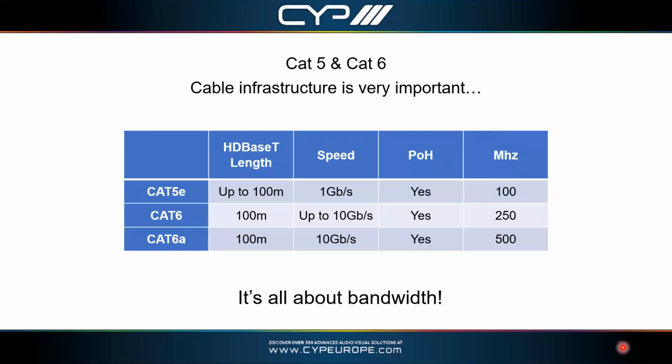Yeah, over the years, Cat5e as standard, they've managed to increase the bandwidth, the megahertz rate. So it's quite common to find a Cat5e that goes up to 250 now, as well as a Cat6. So if your budget's tight and you are going to use Cat5e, then do have a look, because normally for literally a pence or two a meter, you can get something that, whilst it hasn't got the extra shielding of Cat6 and shielded cable, at least gives you a little bit more megahertz, and it's very, very similar priced. It's only, as I say, a few pence per meter more.